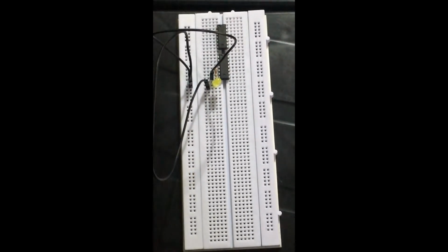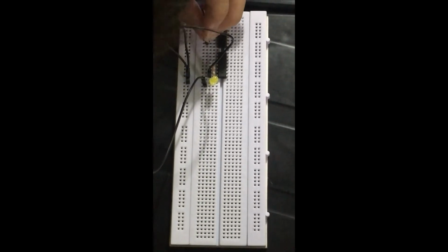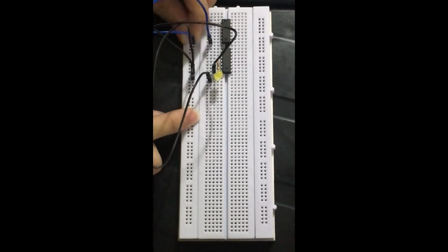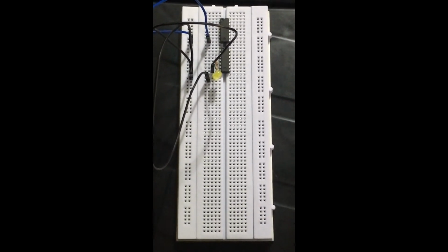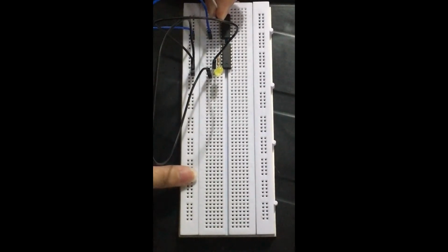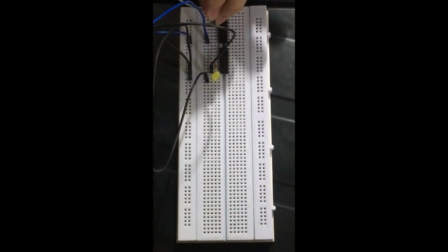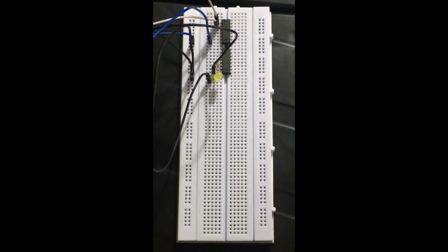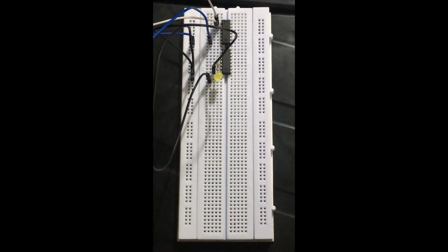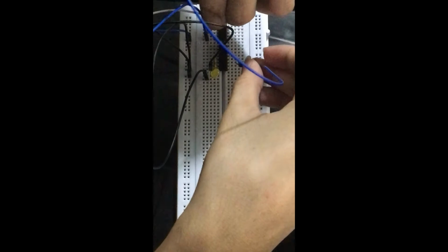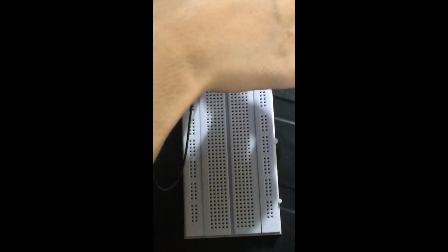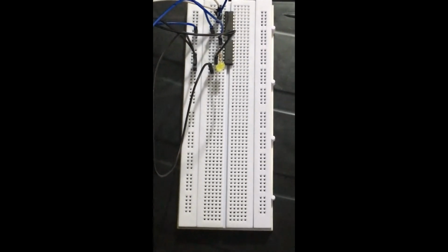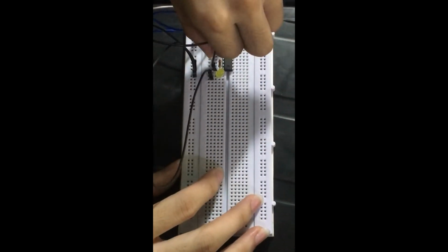In operating, when the inputs B and C have logic 0 in them, automatically it will be logic 0 or the LED is off, because we use the 7408 AND gate. When the input A has logic 1, the LED will be in logic 1 or it will be on, since we are using the OR gate for input A.